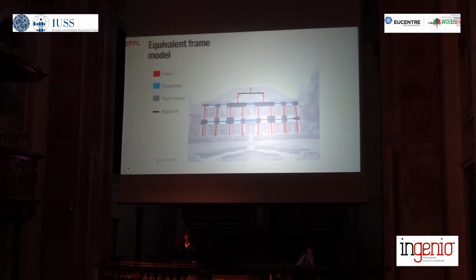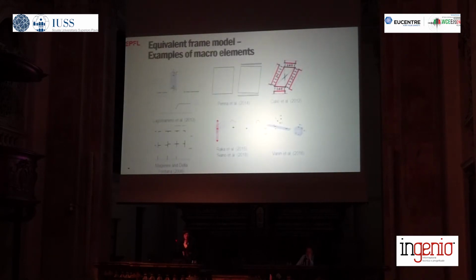A lot of work has been done on that, and many macro elements have been developed, and as I said before, the one by Andrea Penna is probably the one most widely used nowadays in research and also in engineering practice. There's a lot of choice available, but what they all have in common is that they focus on the in-plane response.